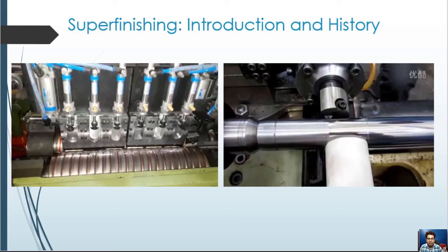The process was originally developed to eliminate Brinell marks from automobile wheel bearing surfaces that resulted from long distance shipping. When automobile wheels were blocked to prevent rolling during shipping, only a few of the rollers or balls in the wheel bearings supported the weight of the automobile. Shipping vibration caused the hardened rollers or balls to press against the bearing component and form slight depressions, a process called brinelling.